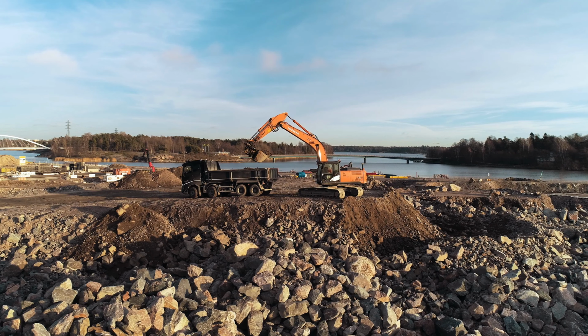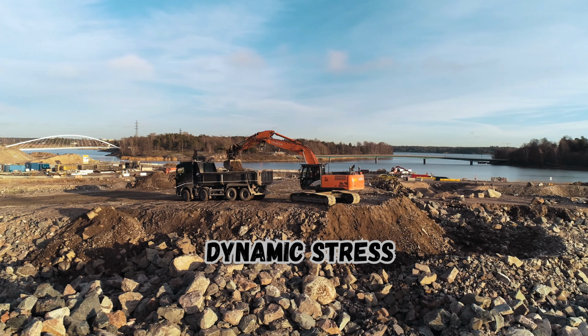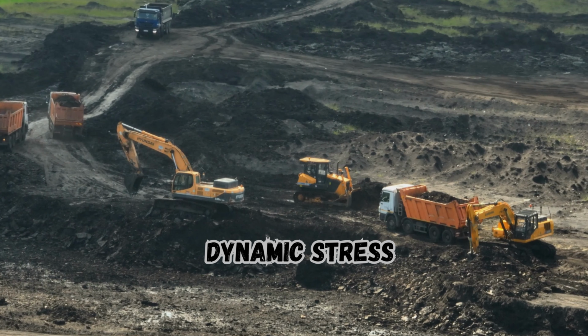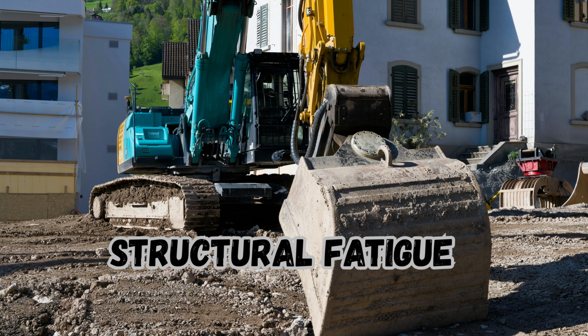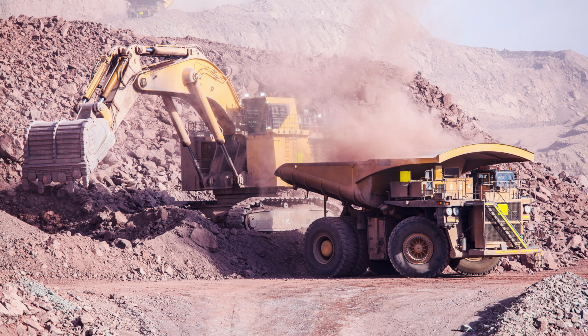At the same time, these changing forces are transmitted through the excavator's structure, increasing the stresses experienced by the boom, arm, and their connecting joints. Over repeated operating cycles, such fluctuating stresses can contribute to structural fatigue if the components are not properly designed to withstand dynamic loading. In large mining excavators, the mass of moving components can exceed several tons, meaning that inertial effects play a critical role in machine design.